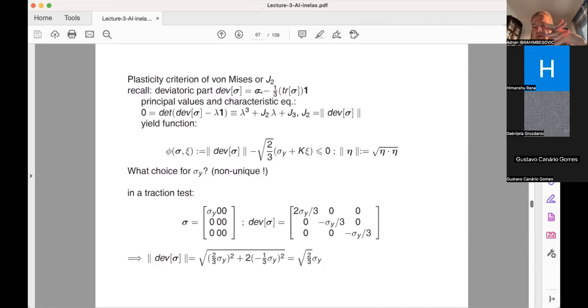It happens that the deviatoric part is conjugate to the change of shape, whereas the trace part divided by 3 is a pressure, in particular something like hydrostatic pressure. It's conjugate to the change of volume. We already said that when we were talking about elasticity in 3D, you can characterize the behavior of elasticity in 3D for an isotropic material with two components, say the Young's modulus and Poisson's ratio, or take the Lame coefficients lambda and mu, or you can take a bulk modulus.